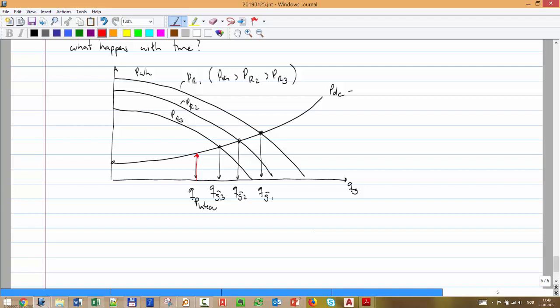At the initial time, you can see that I have more energy than what I need. Therefore, at time 1, reservoir pressure is PR1. I need this delta P. I will spoil the graph anyhow. That will be delta P1. You need the delta P choke 1.